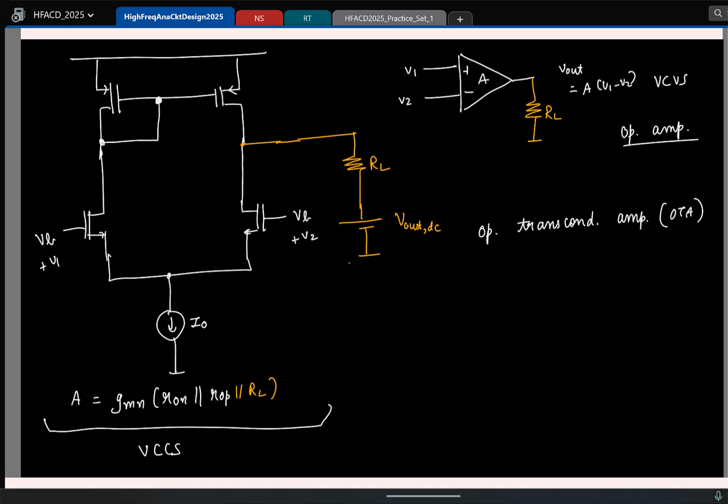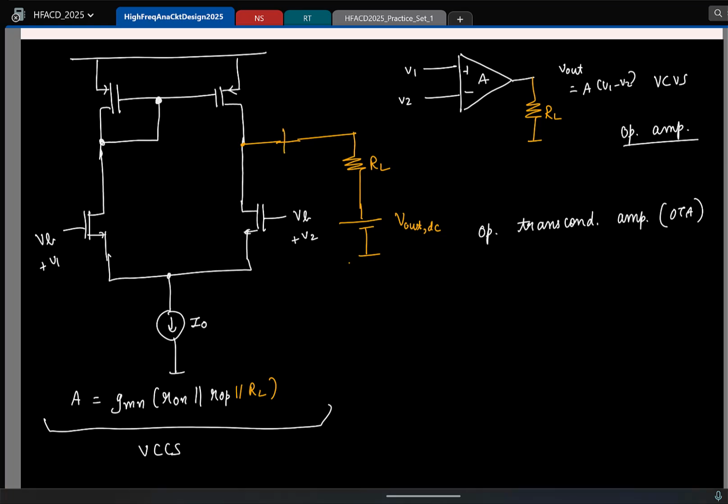Okay. So in the small signal model, we are operating at a higher frequency so that the lower capacitance value is also accepted. Yeah, still you need to have a capacitance, right? Now let's say you're trying at very low frequencies. It is not like you always operate at high frequencies, right? There are a lot of sensor applications, biomedical applications where the frequency is less than 100 Hertz. So then the capacitance required will be really large. Yeah, but like you mentioned, if your operating frequency is large, you can have a reasonably sized capacitance. I'm not saying this is not at all done. This can be done, but in general you try to avoid capacitance.